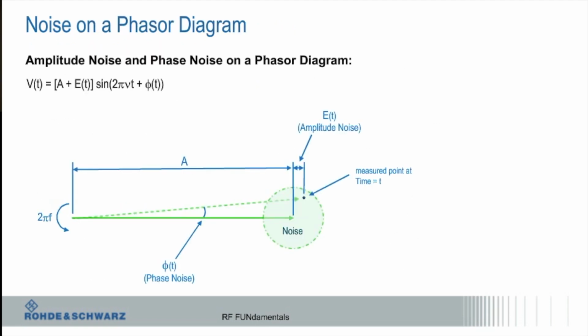So getting into noise on a phasor diagram, what are the components of the noise? If I look at that vector, the green line, which basically is my desired signal, the reality is I'm going to have some errors associated with it. So phi of t of the vector is like a rotational error, right? If you looked at that dot in the constellation, you'll see a constellation in a minute, instead of being a perfect dot in one spot, it's going to move a little bit rotationally. And you'll see it. It's actually pretty cool in a minute. So that's a phase error term.